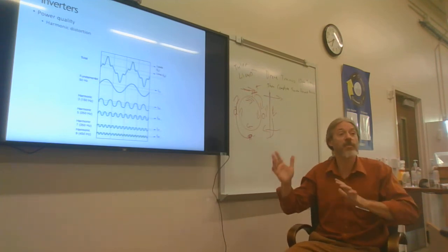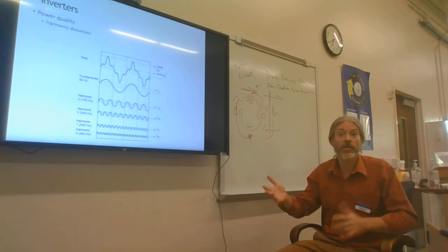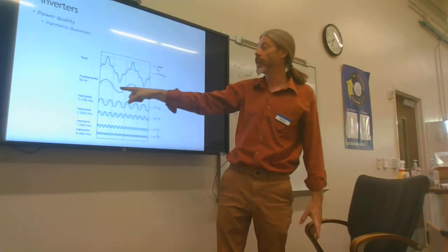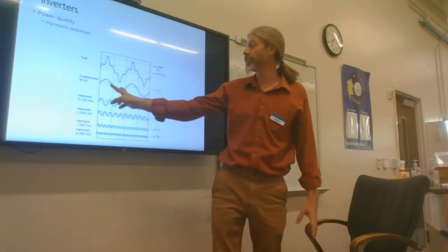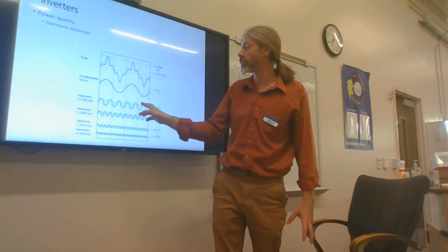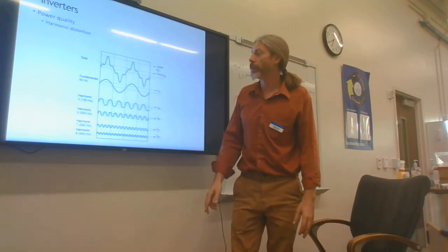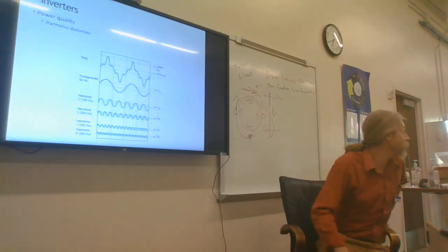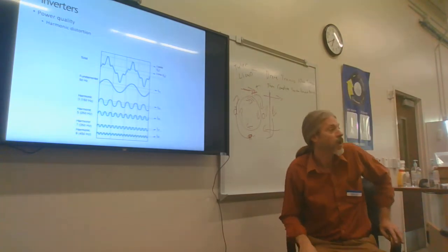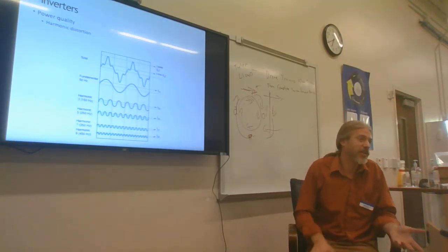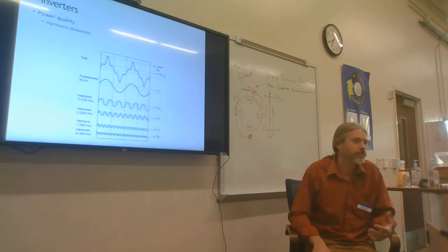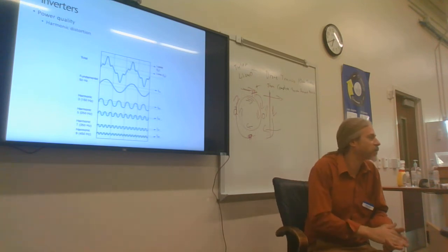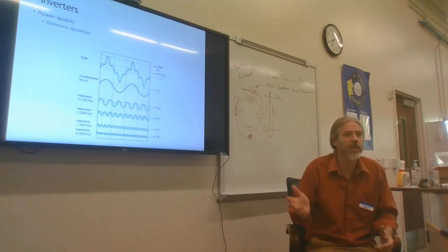We are supposed to have symmetry in multiple ways on our sine wave. To start with, we're supposed to have a vertical symmetry, same distance above as below. We're also supposed to have distance symmetry. How far is each of these? And so, anytime that you do not have appropriate symmetry, then you have harmonic distortion. Certain appliances, this makes no difference on, like your well pump. Your well pump could operate from probably 50 hertz or 45 hertz to 70 hertz.